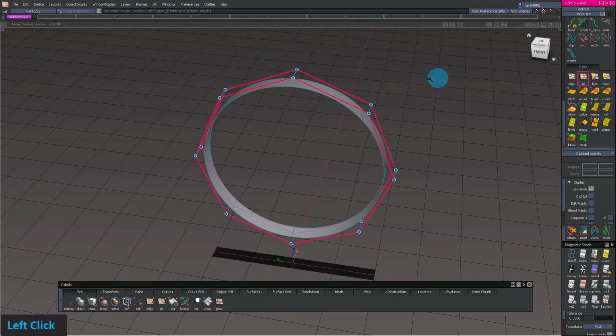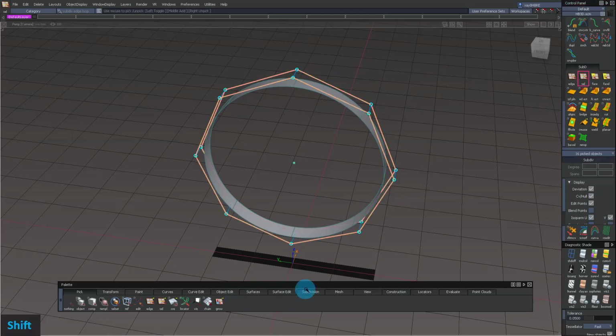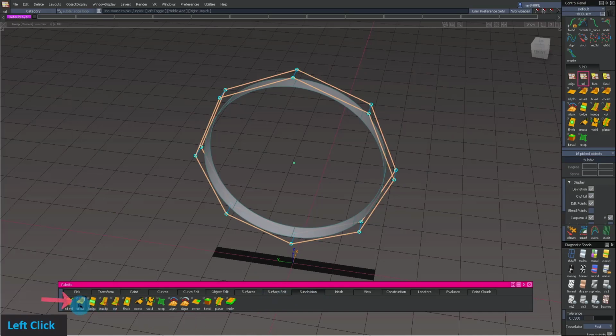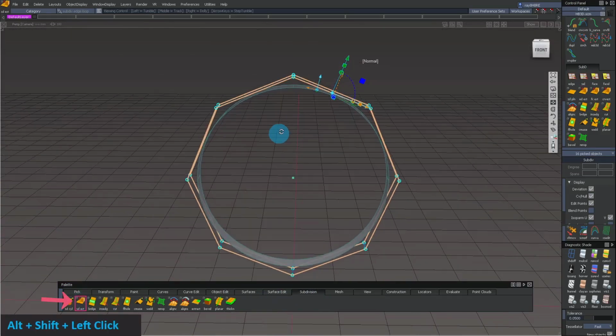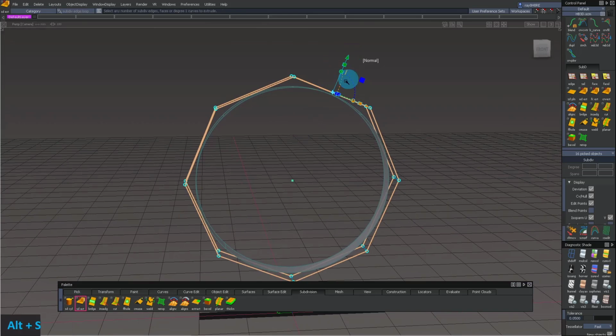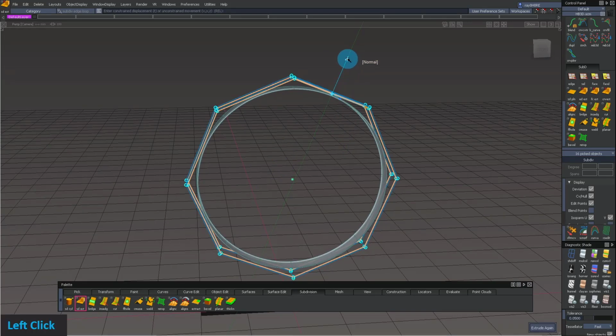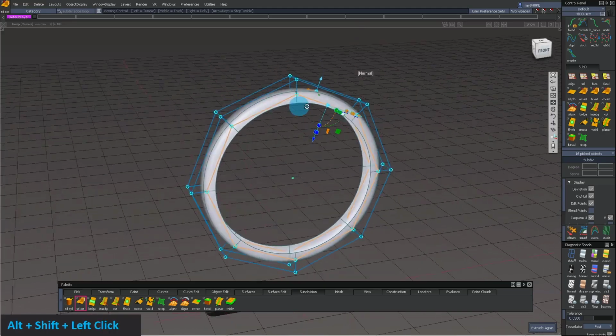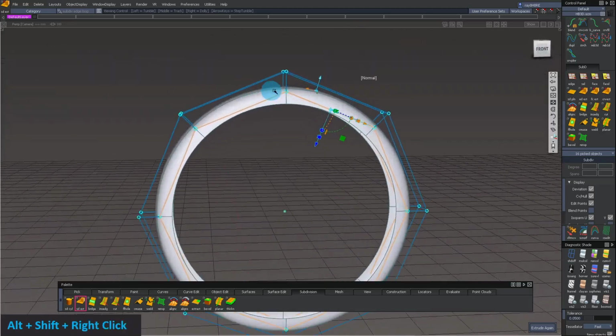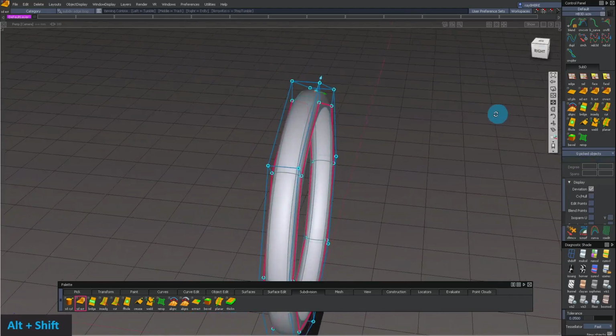So I actually have my Sub D tools here, and that way I can select the whole edge loops. And then I'm going to extrude these. So the extrude tool is right here. If you see, there's this little gimbal, and right now it's based off the normal, which is good. But if you want to change it to more of a global extrude, just click there. But for this one, we're going to keep it at normal, and then we're going to push it down. And that is going to give us the first sidewall of our steering wheel.